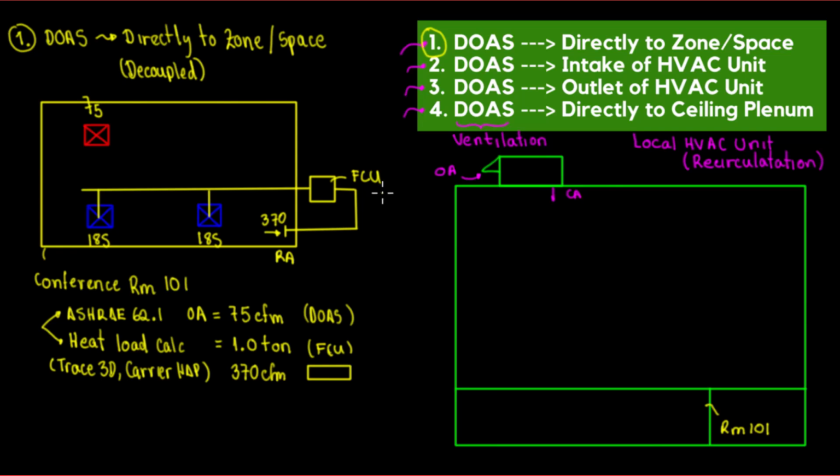And again, this is the local HVAC equipment. All right. Okay, so this is return and supply, right? And you can size the ducts. That could be for another video. Okay, and remember this is above the ceiling tile, ACT, and the unit is outside to avoid noise. If there's no other choice, then you would have to put it inside, which is not a good idea.